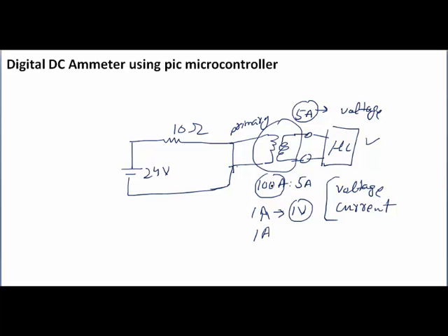So what will be the current at the primary side? We can use this relation to find our multiplication factor. In this case, the multiplication factor is 20. It means if the current is 1 ampere at the secondary, the current at the primary will be 20 ampere. So you can use a current transformer.